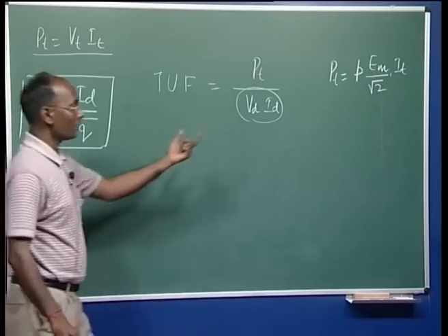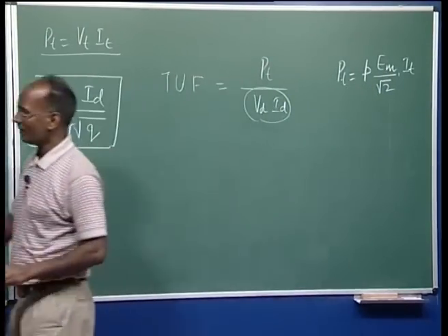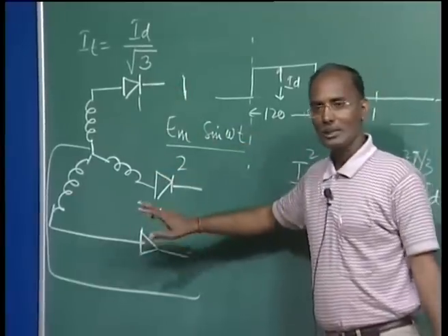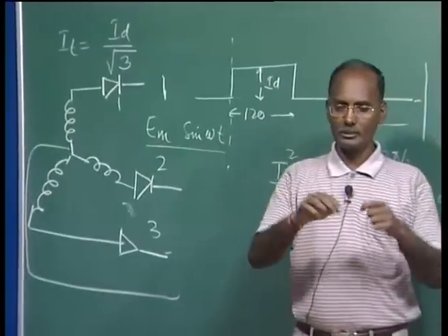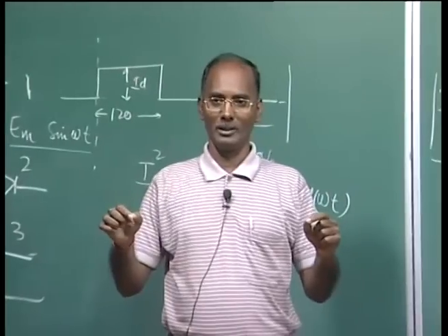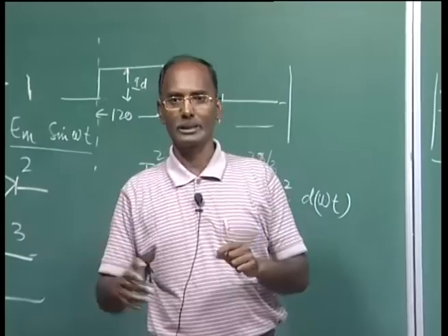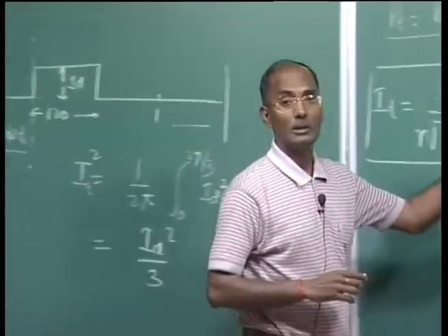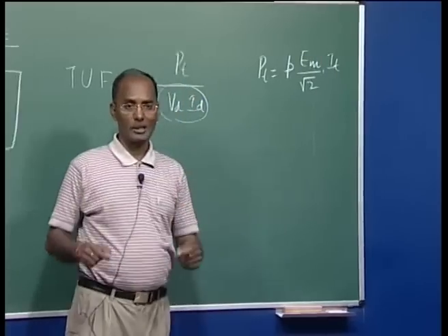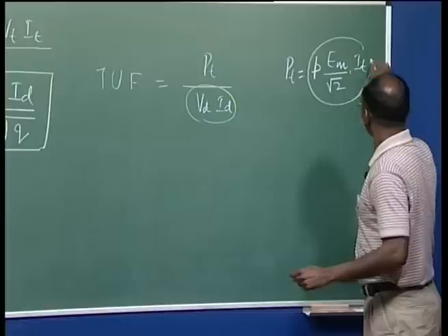Here the number of pulses is 3, so it will be 3. You can also visualize it as 3 phase. So, you can say 1 phase multiplied by 3, but it is not always phase-wise, because some transformers are auto transformers or center-tap transformers. The phases are single, but they are tapped together. So, it depends upon the pulses, which is more convenient than using 3 phase or 6 phase. So, P is the pulse number.